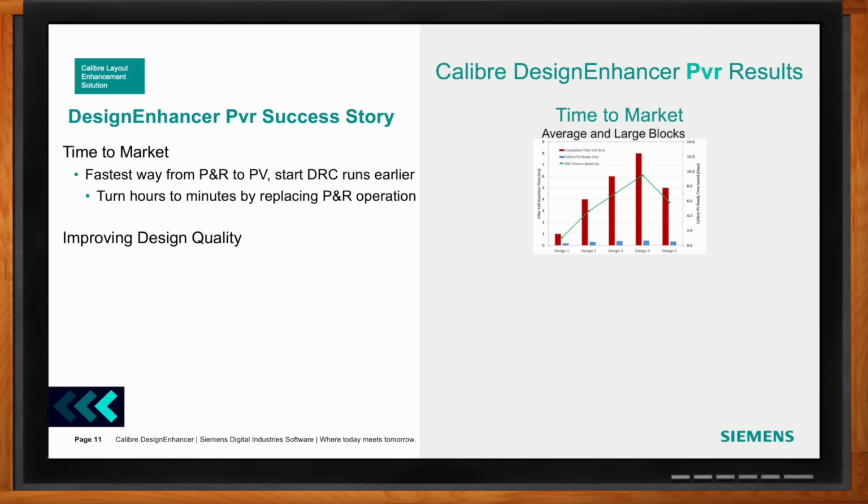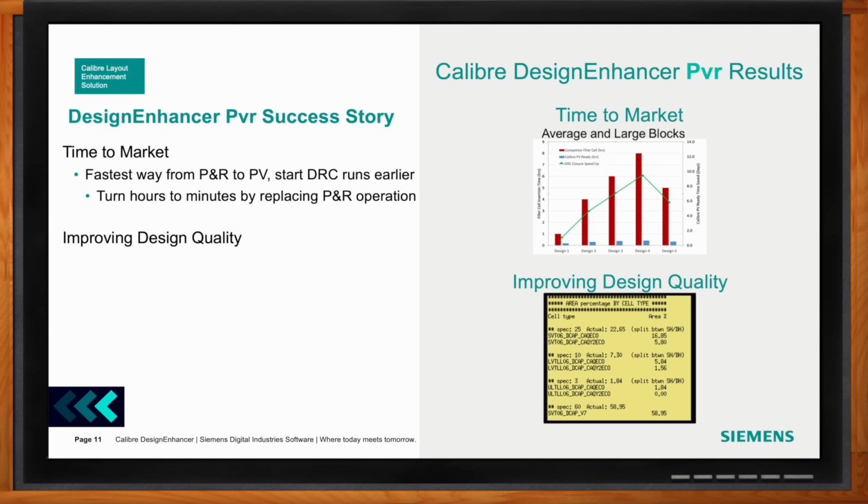and say, you know what? If you can help me place and guide my decoupling capacitors, you're going to be able to really help me with my dynamic IR drop. And so they have come up with all kinds of different ways to specify that. But one of the things they want is for us to achieve certain density targets with the placement of our decap cells.